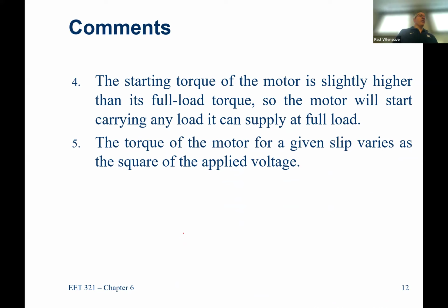The torque varies with the slip, but it also varies based on the square of the voltage. So one of the things that we do with induction motors, if we don't want to start them very hard, or we don't want them to draw a lot of current, is we start them at a reduced voltage. You can actually buy, they're not as common as they used to be, reduced voltage starters that reduce the voltage to like 65% of nominal, which means they pull way less current. They pull a lot less torque out, but as long as it's enough torque to get the thing started, it should be able to get up and running. It's just going to take longer to start.